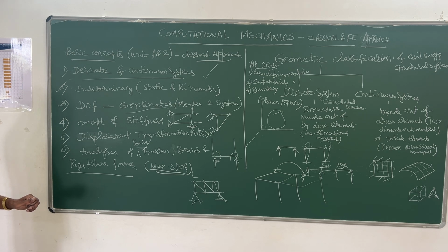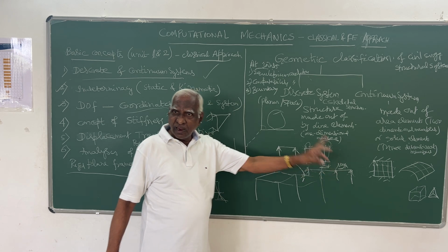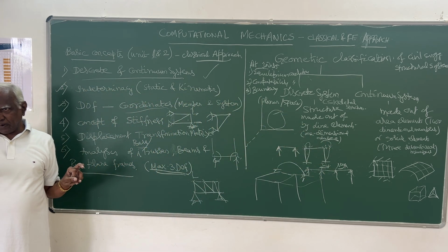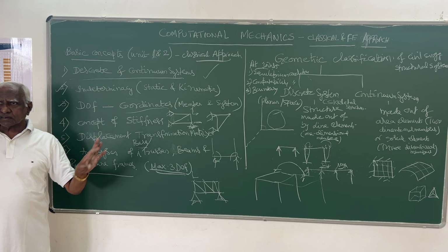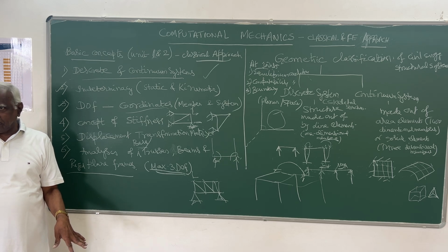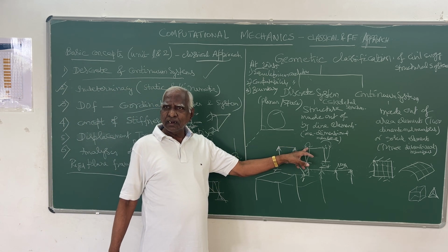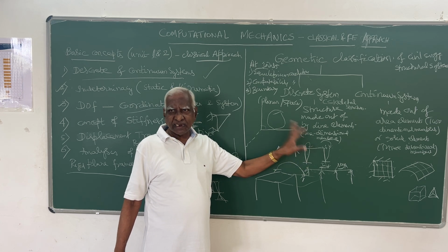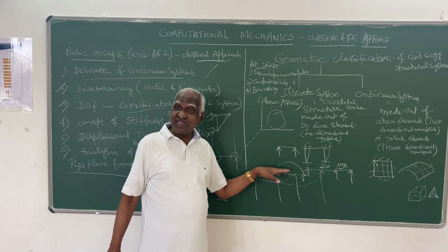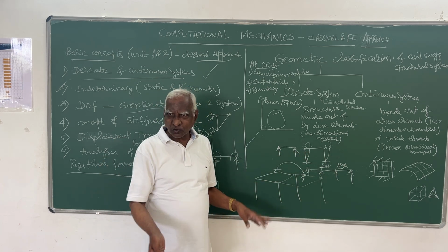So that is about these types of structural systems, and all unknowns, that is displacements and forces. Two types of unknowns. They are considered only at the joints, and they can be either direct force or moments, and generally in a space structure it will be 6, whereas in a planar structure it reduces to 3 in general. Out of that 3, in rigid plane frames, all 3 can happen at each joint. In beams, we assume the beam to be axially rigid, so only 2, vertical and rotation.